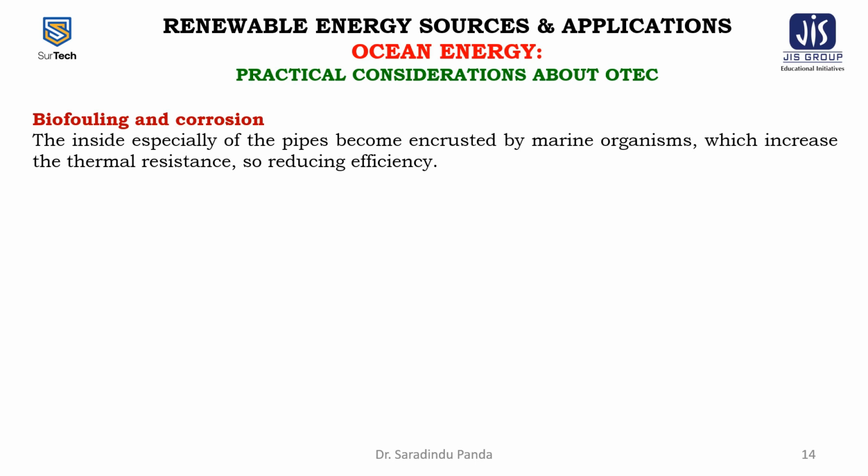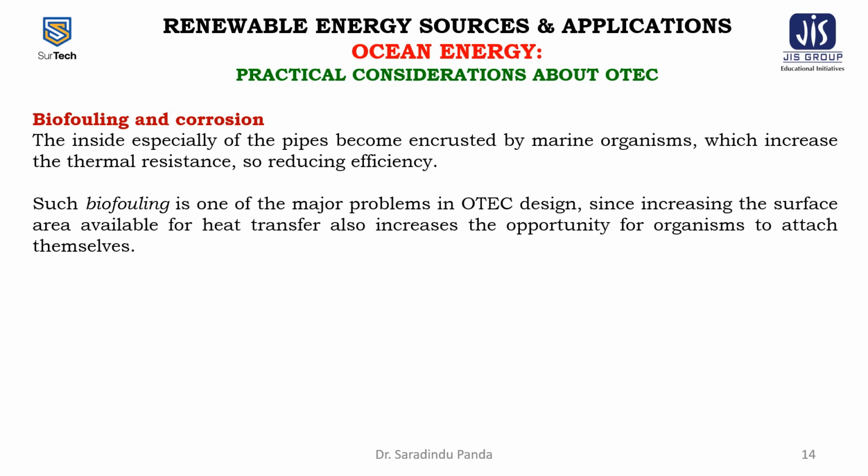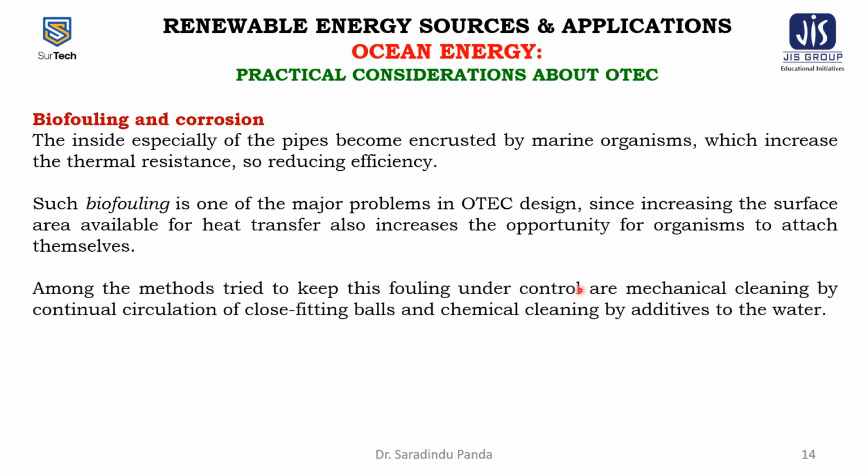The second consideration is biofouling and corrosion. The inside especially of the pipes becomes encrusted by marine organisms, which increase the thermal resistance, so reducing efficiency. Such biofouling is one of the major problems in OTEC design, since increasing the surface area available for heat transfer also increases the opportunity for organisms to attach themselves.